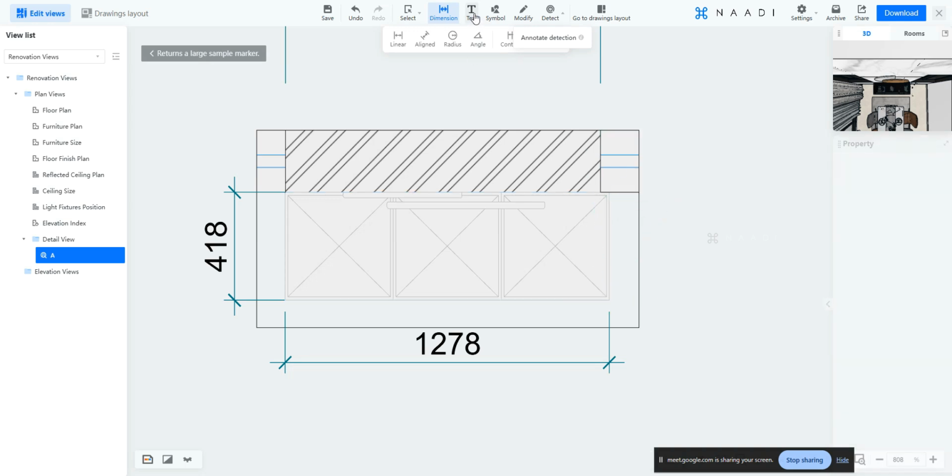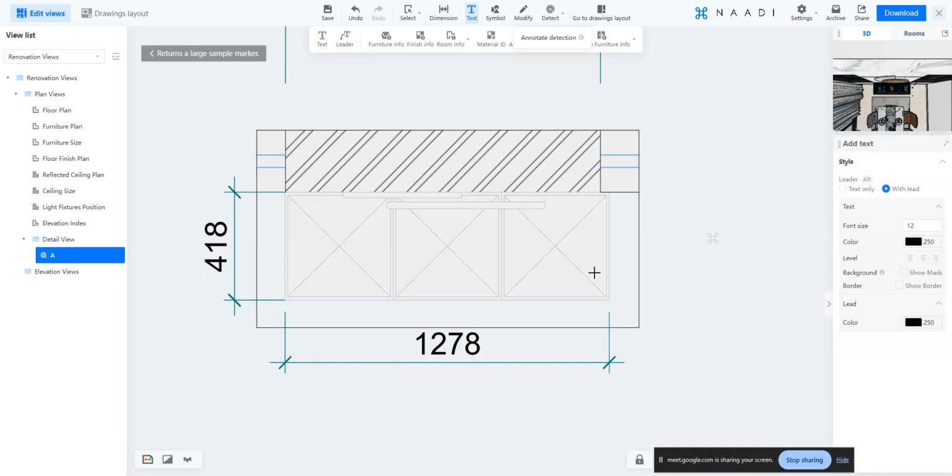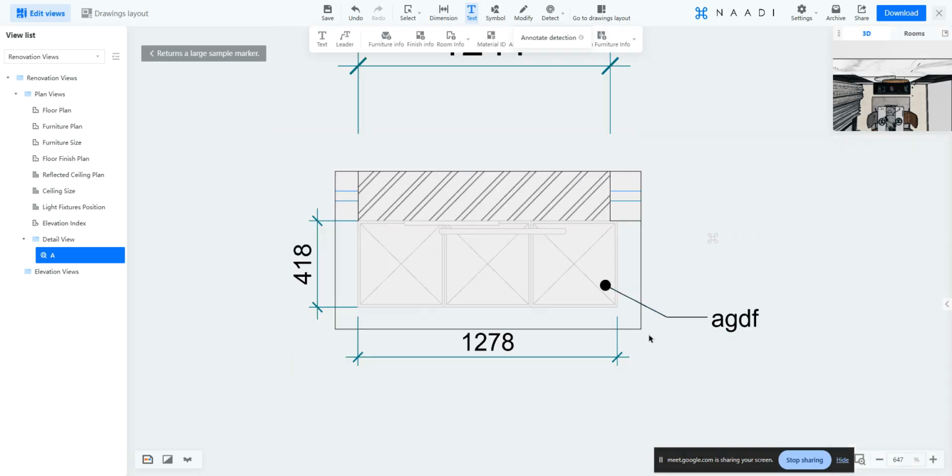If you want to just add a text here, and you see those texts will also be added. Okay, so this is like, if you want to add a detail of a specific component in that plan, yes, you can add a call out view. Okay, and can you see it is added under a separate tab here named detail view, right? You can use it. So this way, if you want to add a call out, yes, you can also do the process too. Okay. So this is what your call out tab here is, and now we can take it forward.